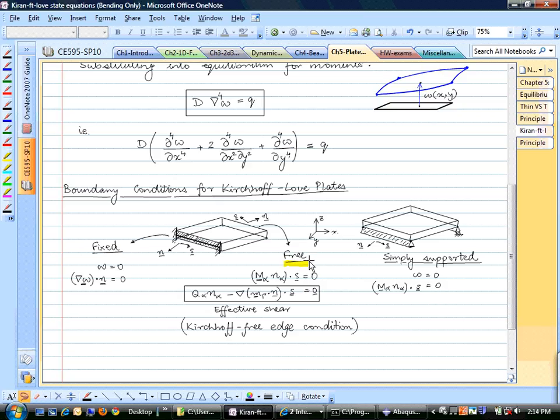And the free face boundary condition is actually a little bit tricky. It so turns out that when you write out the weak form for this free boundary condition, the derivative of W with respect to the free face in the normal direction is not independent.